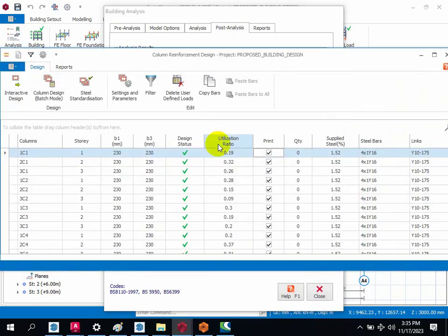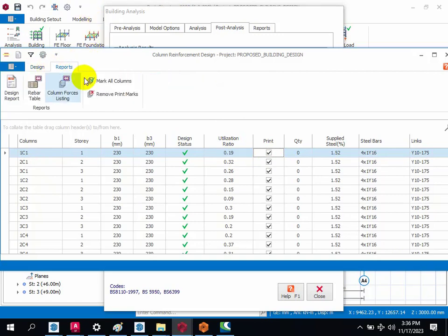In the column, from experience, if you print all this, by the time the report is printed, it will look like a textbook. It will be too bulky. It's not necessary. You are repeating the same thing over and over again, because we have a lot of similar columns. If you know that all your columns are similar, all you need to do is uncheck all this. You can uncheck them and specify the particular one.